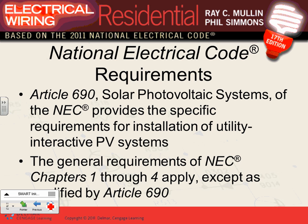Okay. Wiring methods that they use, guys, are the same wiring methods that we use in Chapters 1 through 4, with some modification for the PV system. The PV cables have to be rated for PV use, for the DC.